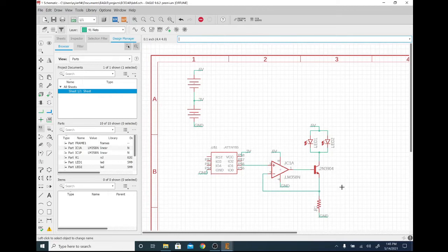So 40 milliamps with a 3 volt drop, let's see, 3 divided by 0.04 is the same as 300 divided by 4, which is around, oh goodness, math, don't fail me now. Let's see. If we divide it into quarters, that would be 25 times 3 is 75. Okay, so we need this to be a 75 ohm resistor.